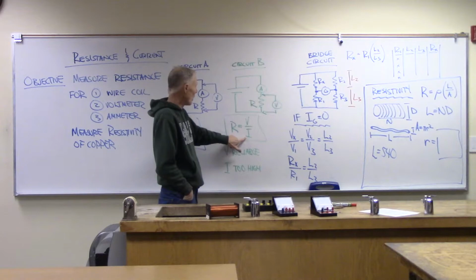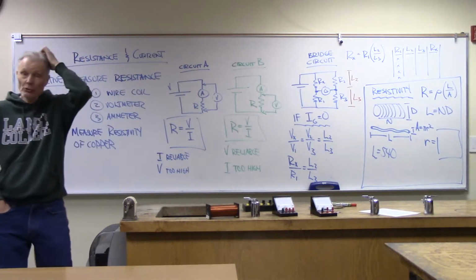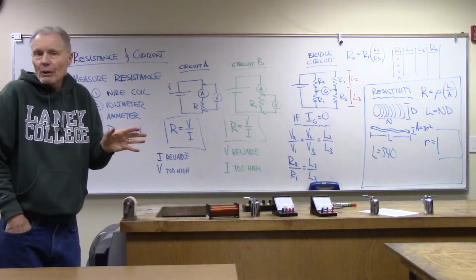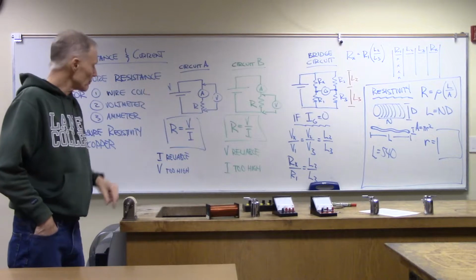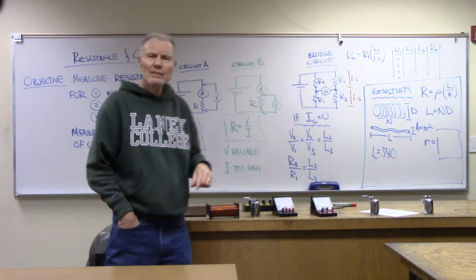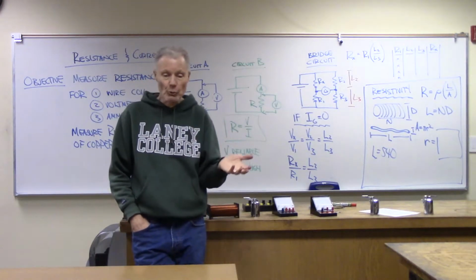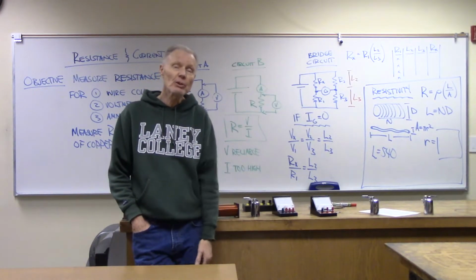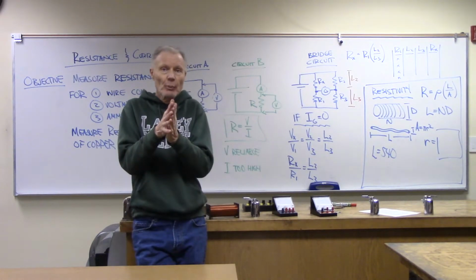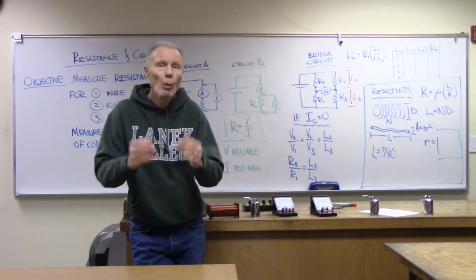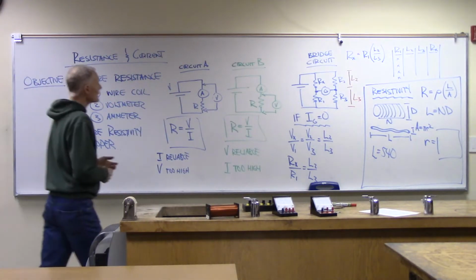And that also will give me a false reading, but one that's too low. So one way we could approach this is to do both, circuit A and circuit B. We're guessing that for circuit A the resistance calculation will come out too high, and for circuit B the resistance calculation will come out too low. And we'll take something in between and hope that there's not too wide of a range there. All right, so that's what circuit A and B are going to look like.